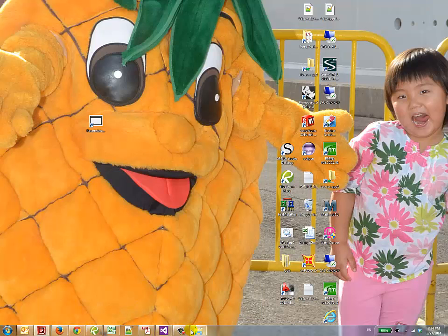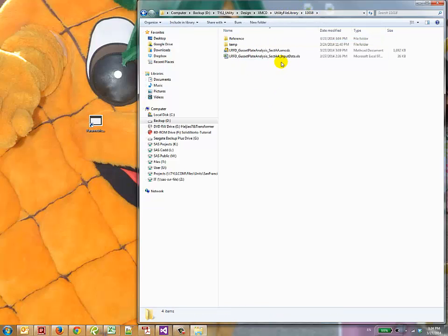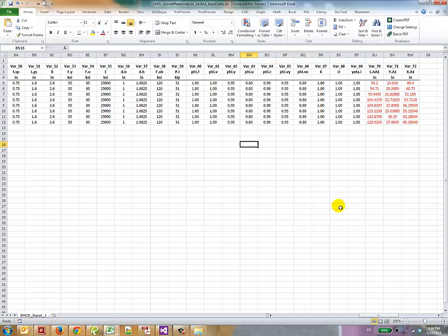use this working folder to automate the design process. You need a Mathcad sheet, which is the section AA portion of that New York DOT Mathcad sheet, and you have Excel sheets that provide all the design scenarios for parametric design.